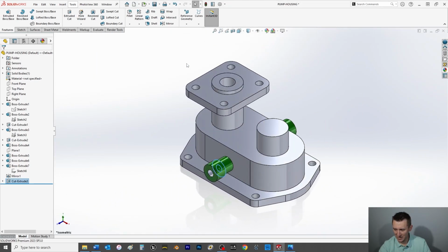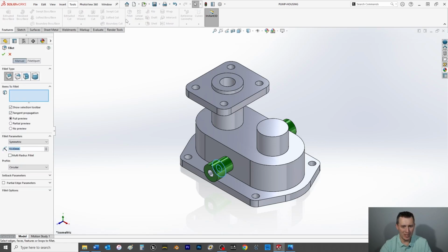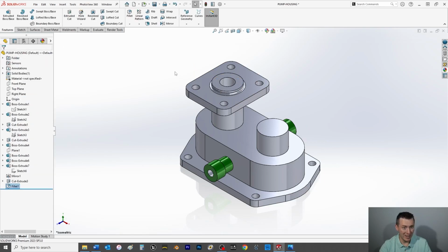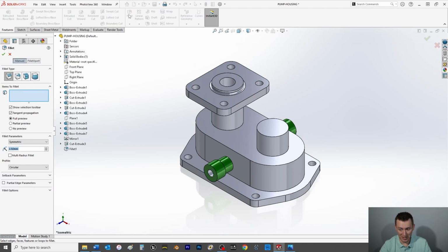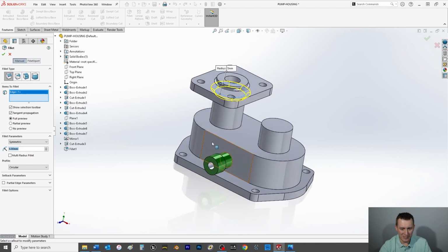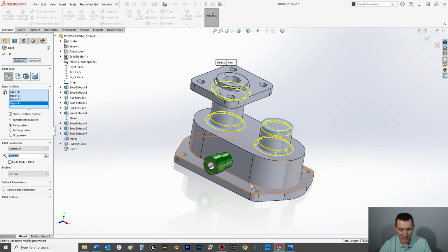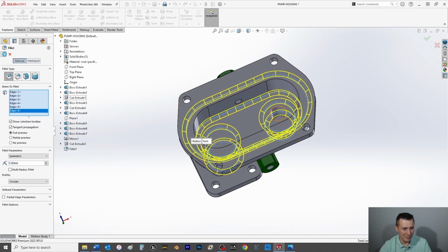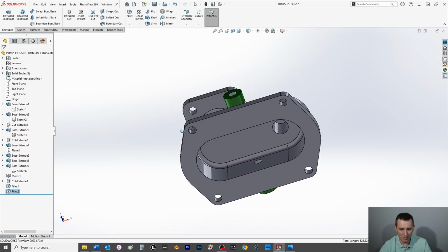And then we're going to bring it isometric here. And let's finish this up. We only have one unique radius here of 2.5 for a fillet, which is this here. And now we're going to really group everything together. So the other one is going to be 5 mil, and it's this surface. This edge, this edge, this edge, this edge, this edge, and this edge. And boom.